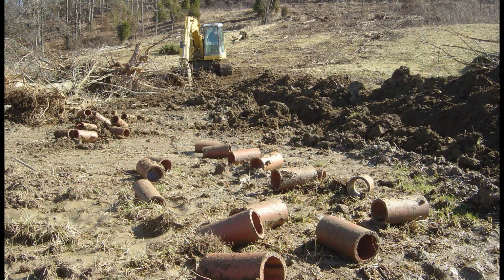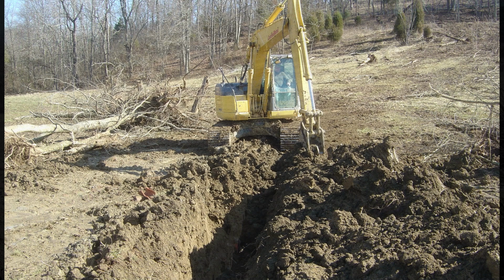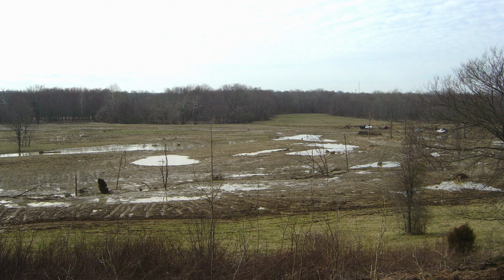The clay drain tiles were installed on this hillside with a 6% slope. We were able to drive over this field in two-wheel drive vehicles, even though it was a wet time of year. After we removed the clay tiles and compacted soil in the trench, we couldn't go close to the field in a four-wheel drive vehicle because the soil was now saturated.